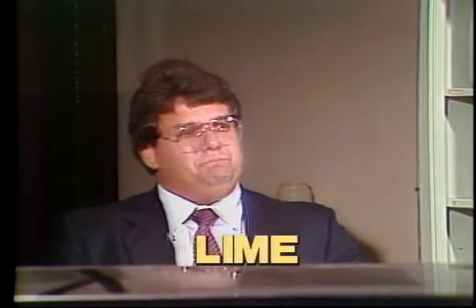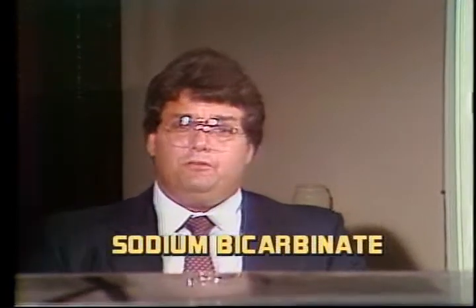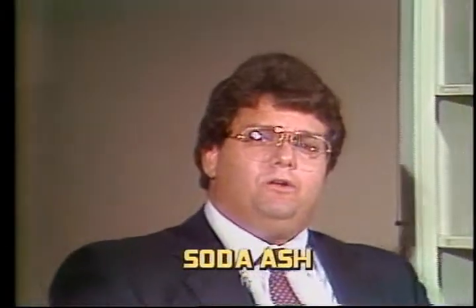The mud engineer may ask you at some point in time to add a few sacks of lime or sodium bicarbonate or soda ash to the makeup water, which will precipitate out any of the insoluble contaminants. In doing that, it prepares the water so that when you add the bentonite, you'll get the viscosity that you want.